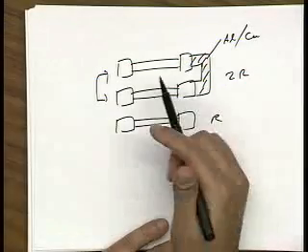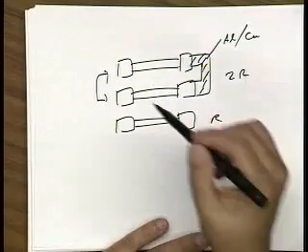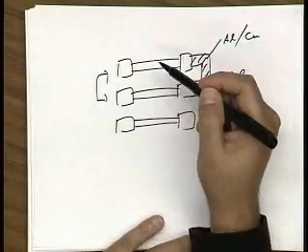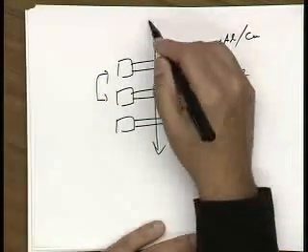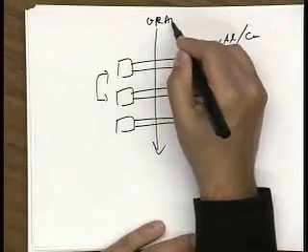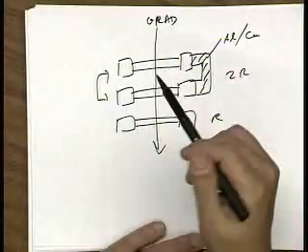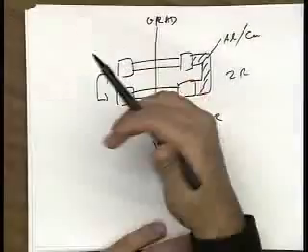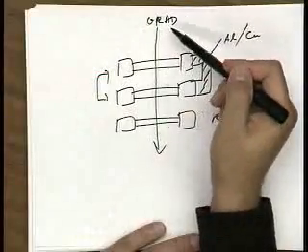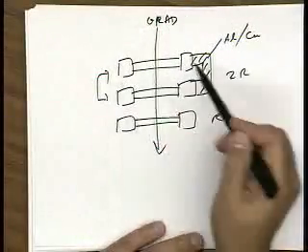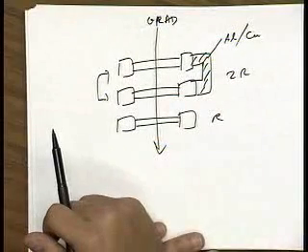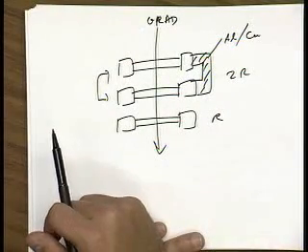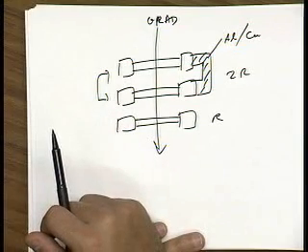So I've taken care of the systematic variation, but I still have a problem with gradients, right? So if the doping gradients are here, right? Imagine this as like a hill. So let's say the doping is higher here than here, then this is going to have lower resistance than this guy, right? The unit elements. So what could I do to take care of that?